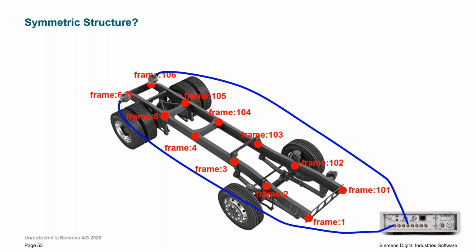Another good example of that from my past experience is if you're working on an automotive vehicle, if you're doing a full vehicle modal, you might have 100 to 120 different accelerometers that you're putting every which way upon this vehicle. Or if you think back to that large plane when we were talking about the free suspension, if I'm putting 100 or 200 different triaxial accelerometers on that structure, I need to have a method that's going to help me lay these channels out.